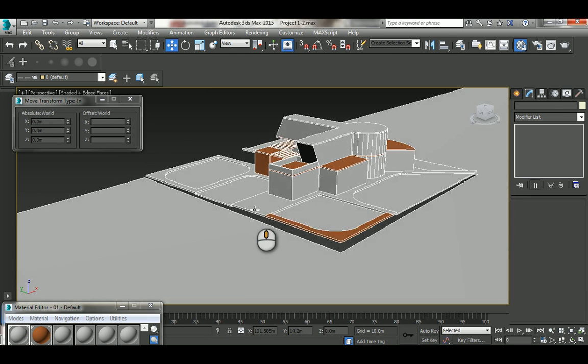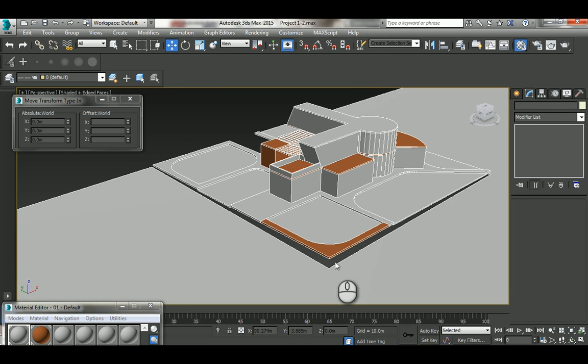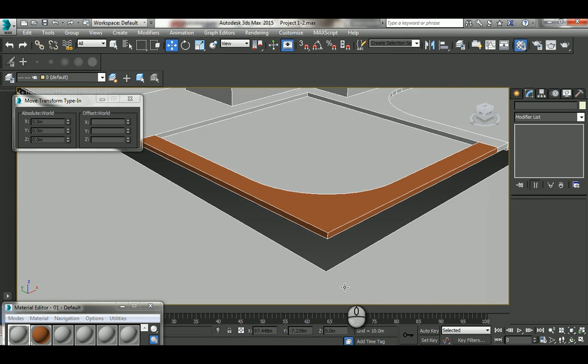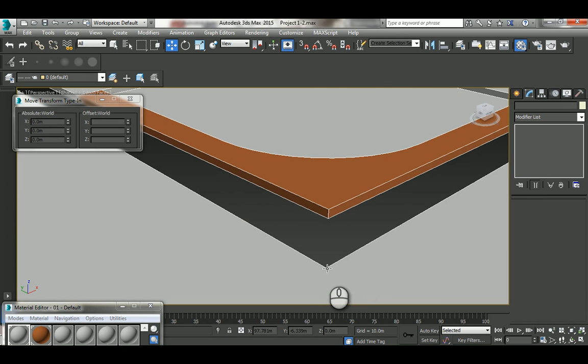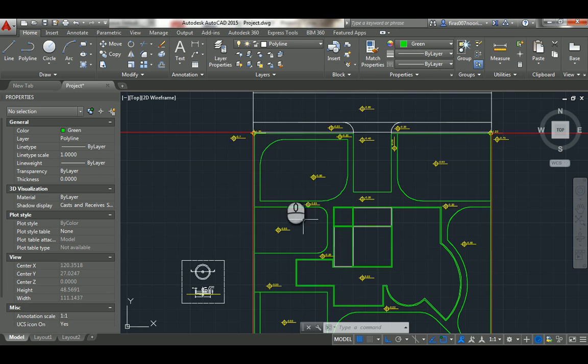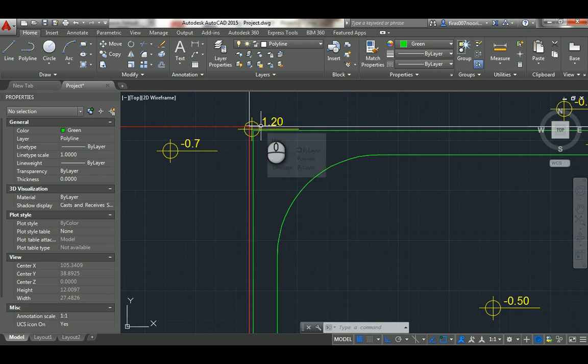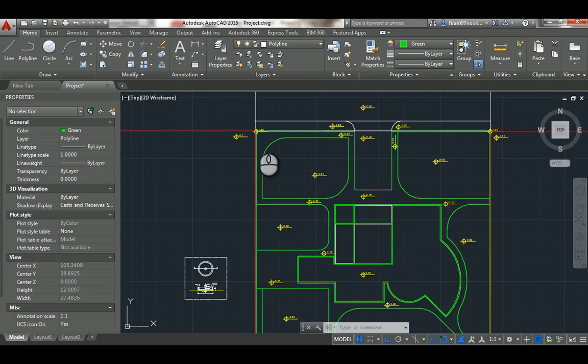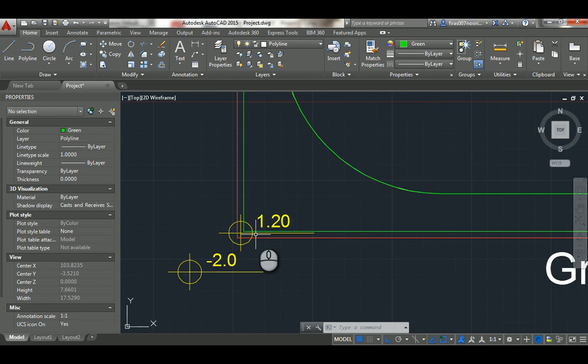But again, we need to make a wall, the fence actually, that is able to not show any gaps. So the lower point of our external wall or fence should be starting from the lowest point, while the highest point is given to us here, which is 1.2. So we have to take the Z value of the lowest point of the wall minus 0.2 and the highest to go to 1.2.